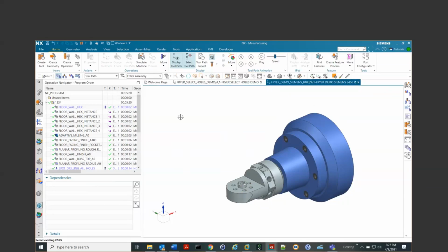Once again, under the feed rate, you would have to type in MM, whatever the pitch is, and close the parenthesis and make that IPR, and it would do the conversion. Okay. So we would just convert the geometry of the taps to an inch value. That makes sense. Right. You convert. Okay.